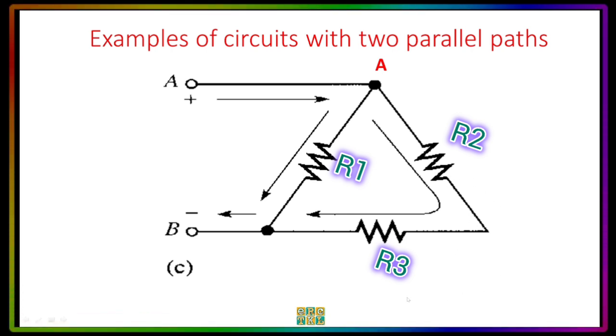So you have to get the sum of R2 and R3 before you can get the parallel RT of the other resistor on the left and the total resistance of R2 and R3. But we will see that later when we discuss series-parallel circuits. So actually, this is not only parallel. Again, this is two resistors in series, and after you calculate the sum, it will become one. Then it will be parallel to the first resistor.